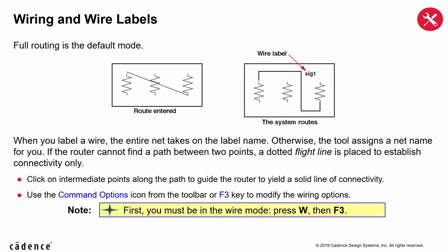You can choose from different draw modes. Full routing is the default mode, and the route draw mode chooses any 2 points in your design, and then it automatically routes a wire around components. If a routed net remains dotted, it is because there is no clear routing channel. This can happen if the instances are too close or they overlap the selection boxes. To solve this, move the components further apart to give a routing channel. More information on route methods is included in the schematic editor reference documentation.